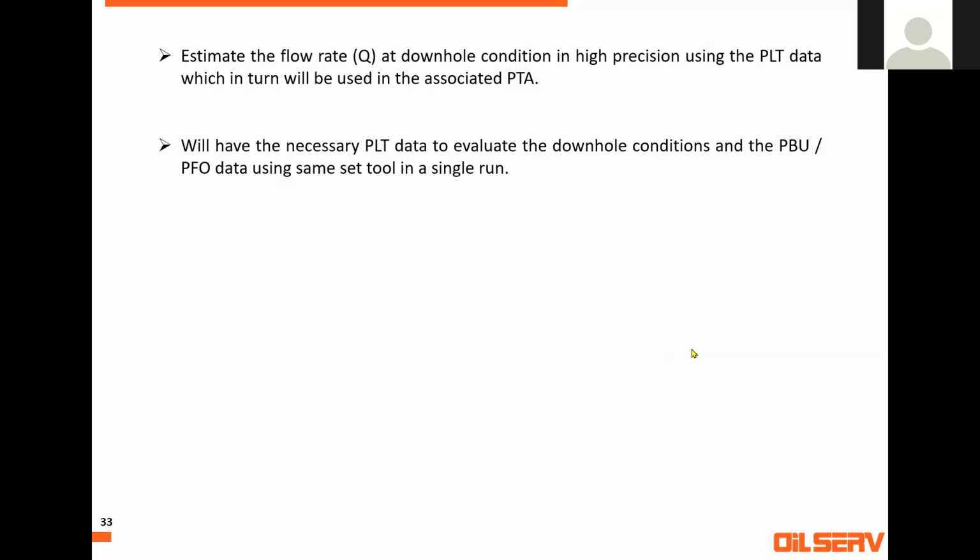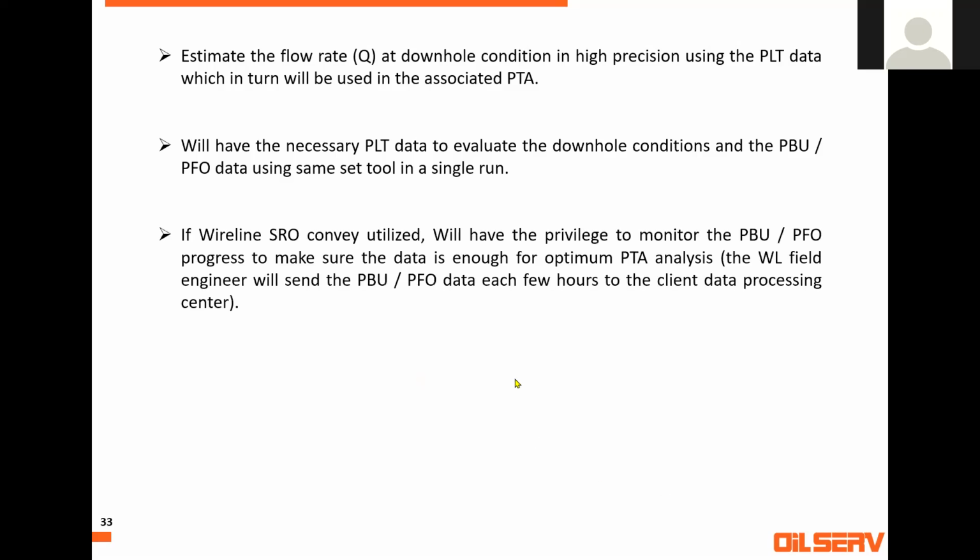The second one: you will have all these data, PLT, PBU, PFO, using the same set of tools in a single run. No need for a separate run, no need to spend more time or rig time. If wireline real-time conveyance and analysis is used, this gives you a real privilege to monitor your PBU, PFO progress.